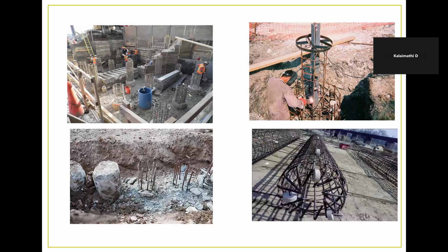In this background, if we look at the available options, we have to select the type of foundation from bored piles, precast piles, and micropiles. Out of these, bored piles are most costly in general when compared with the other two types. Depending on the nature and the type of the loads from the superstructure, the selection of piling type is made. Further, when these types of foundation are constructed, it is advisable to get the recommendation from the geotechnical engineer. But usually we are not going into it.